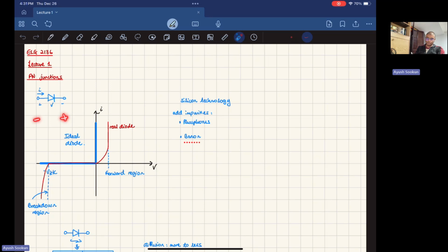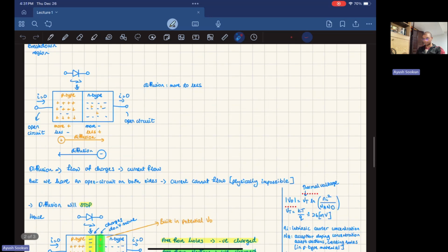So if I have some voltage much bigger than VZK in the negative end, say maybe here, that current is going to start to flow in the negative, opposite direction. That's why we call it the breakdown voltage, at which the diode starts conducting current in the opposite direction. So let's move on.